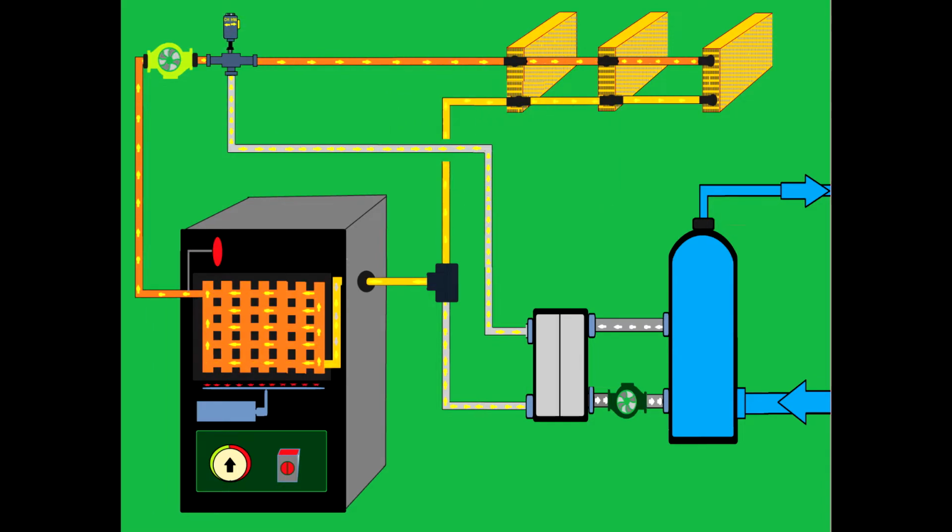Once the heating has been initiated, the water in the installation starts to heat up. We probably all know that we have a thermostat that controls the heating, and we have an overheating thermostat. In case the heating agent overheats, the system will be turned off, and that type of fault will be latched.